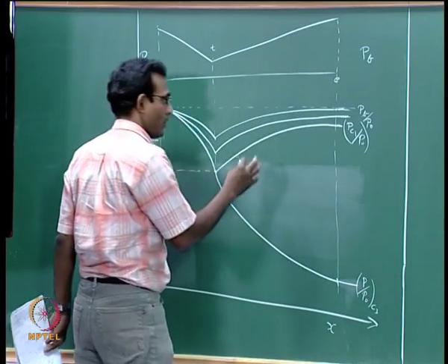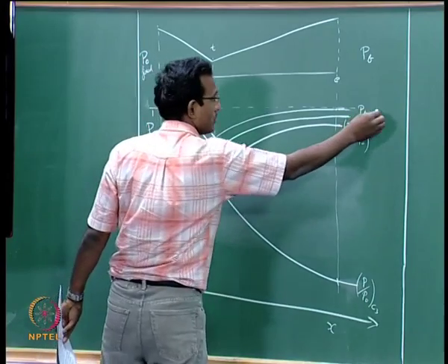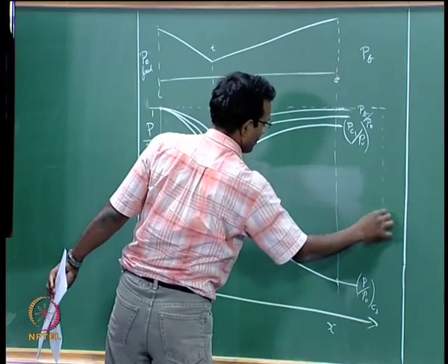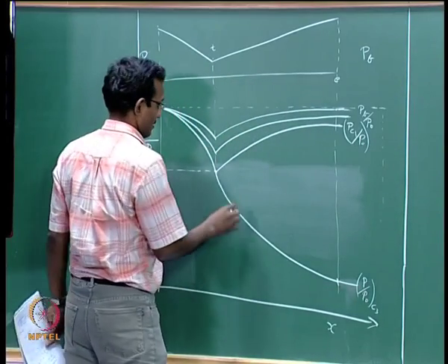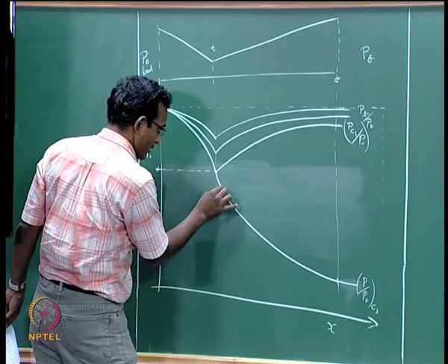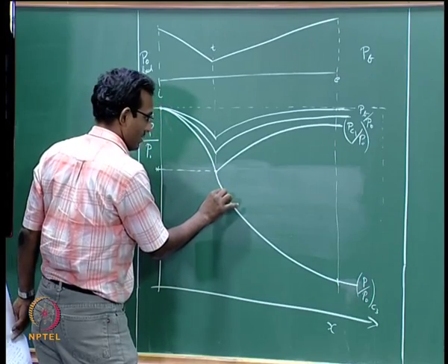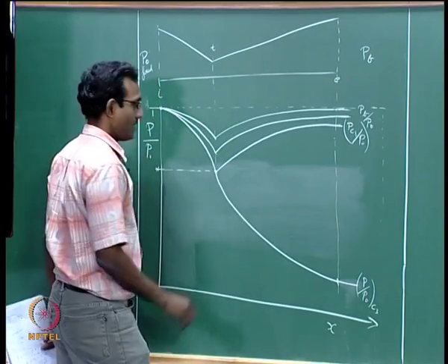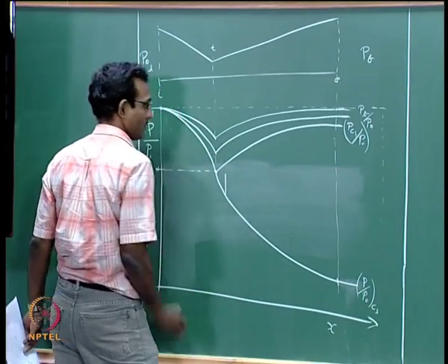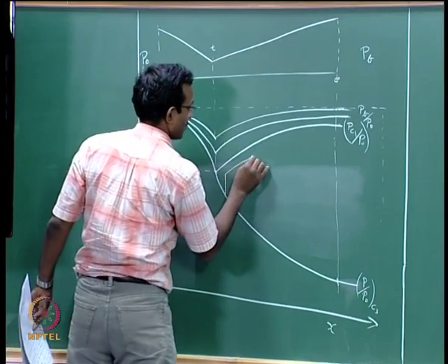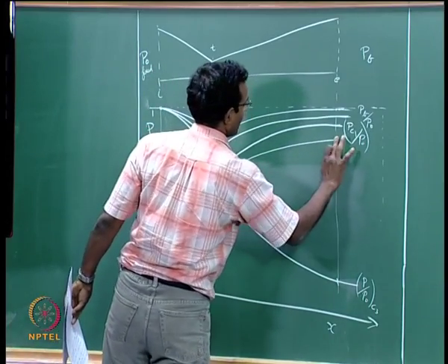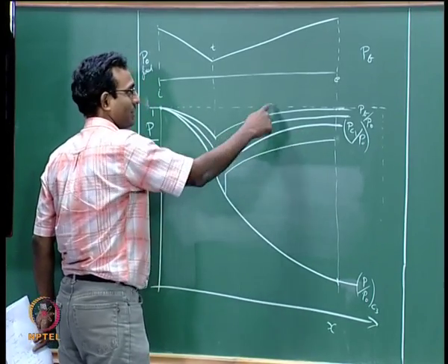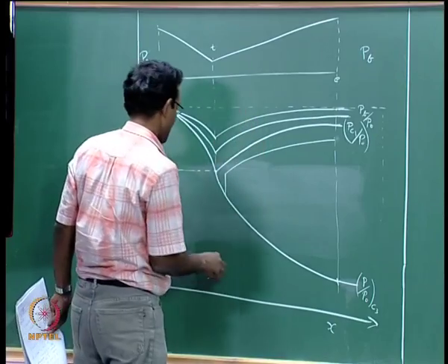Okay. So, if I go through the process of starting from Pb by P0 equal to 1 and going down slowly, I will go to a point where suddenly the flow becomes supersonic partly, and then it realizes that it cannot reach that pressure. So, it goes through a shock, becomes subsonic, and then goes on a subsonic line. We already know that if it is subsonic flow in a diverging duct, it is going to increase in pressure similar to these curves. We already have subsonic solutions.